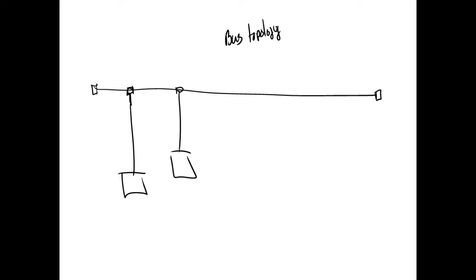Now they still use the bus topology, but they do it a little different. Now what most of the time you'll see, they'll do it as what they call a daisy chain. So what they'll do is they'll come out and there'll be a connector, and then the connector will have another connector on the back of it, and then this will plug into the unit, and then this will daisy chain it down. So this is still a bus topology, but they call it a daisy chain bus. And we could go over there and look at the Amatrol line, and you could actually see, well, that's not true. We got it torn apart, but it uses a daisy chain bus. It's called Profibus is the term they use for that.